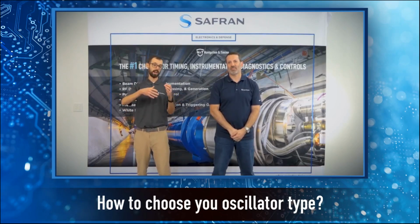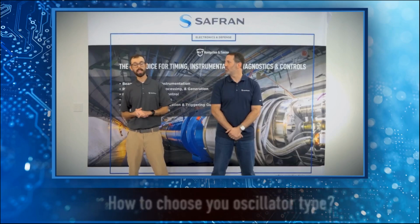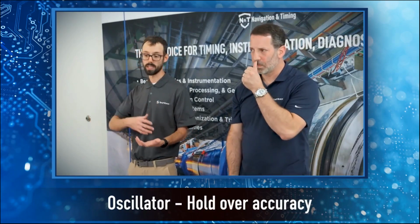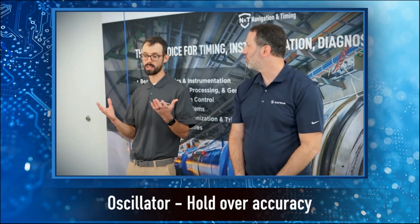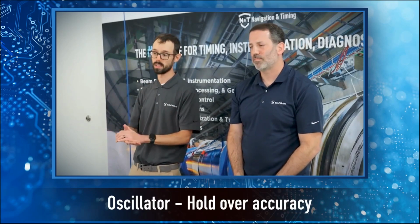Looking back at either of those options, the main thing you would look at when choosing an oscillator type is its holdover accuracy. There are several factors that come into that, generally based on the application that will drive that choice. It's really how long the device can run without a reference, without somebody being able to go in and synchronize that oscillator.